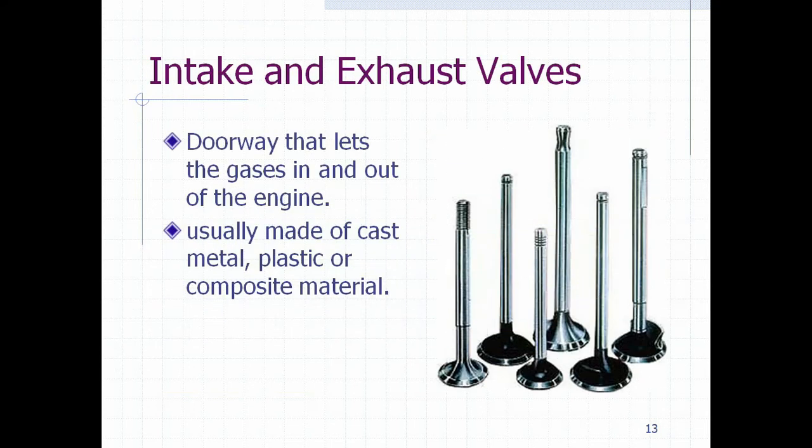Intake and exhaust valves are used to allow the flow into and out of the cylinder at the proper time in the cycle. Most engines use poppet valves, which are spring loaded closed and opened by camshaft action.